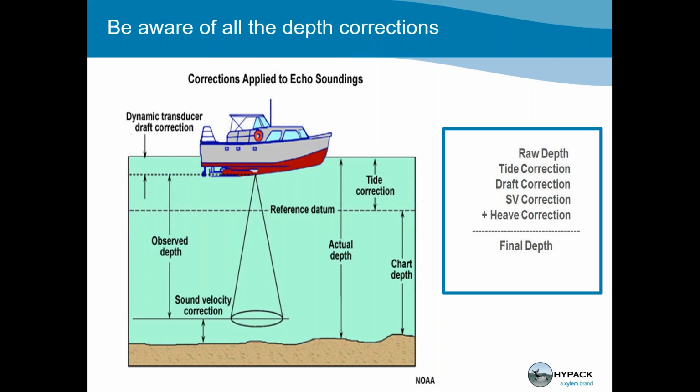The third of the components to look into is your sound velocity corrections. The sound velocity part is very crucial for correcting for error in different water bodies, because you got freshwater and saltwater, and in certain estuaries you got a mix of both. Sound velocity errors can very much lead to sometimes a few centimeters of error, and also in some very bad cases it can be a few meters. So it is always good to pay attention to this during surveys, and I will explain more on the different methods to do so in the next slide. Can I have the next slide, Boris?